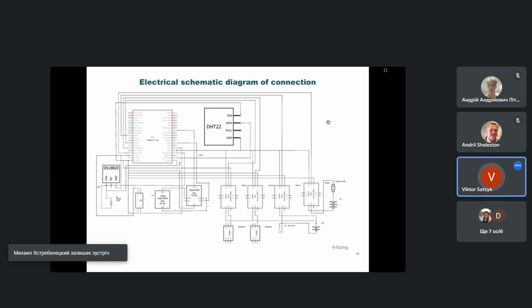The microclimate of the greenhouse is formed by all systems of engineering equipment: artificial lighting source, carbon dioxide supply, irrigation system, ventilation, and heating. To optimize the growth of plants during their cultivation, it's necessary to ensure the optimal ratio between humidity and temperature in air and soil, carbon dioxide concentration, and light intensity. Humidity and temperature in the greenhouse are measured by the DHT22 sensor. It transmits the received data to the microcontroller in the form of a digital signal over a one-directional bus.